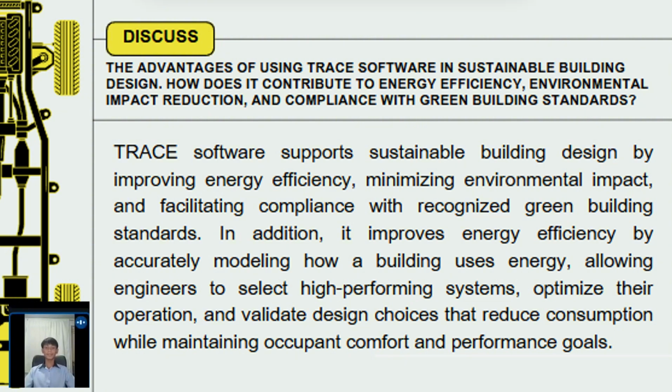Trace 3D Plus uses the EnergyPlus engine and a 3D BIM-integrated interface, offering more detailed energy modeling, faster cloud-based simulations, and better visualization for LEED and ASHRAE compliance. So in short, Trace 700 simplifies the system for faster modeling, while Trace 3D Plus simulates them with more detail for higher accuracy and design flexibility.